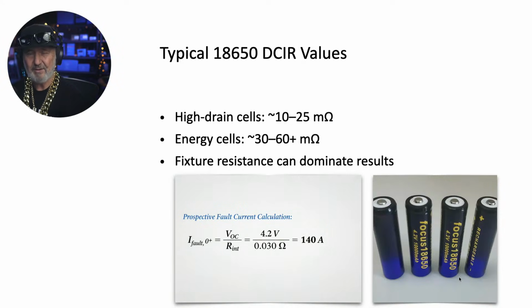That's a massive 140 amps out of that little 18650 cell, which is only slightly bigger than an AA cell. Wow. You can see why they can start fires in rubbish trucks. Those little vapes often have a small lithium cell, about half the size of one of these, and they can create quite a big spark and set fire to things. So there you go.